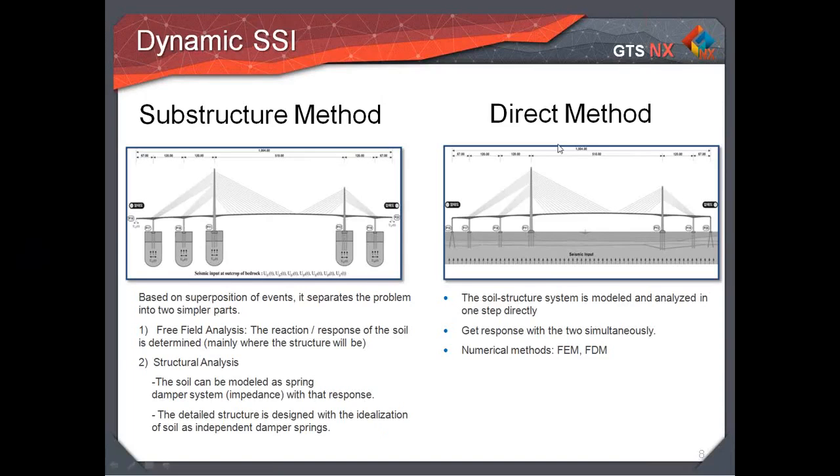The other method is the direct method, in which we basically model the ground and the structure together in a single step, and we solve them simultaneously. And for this, you usually need a very powerful tool, like finite elements or the finite discrete method.